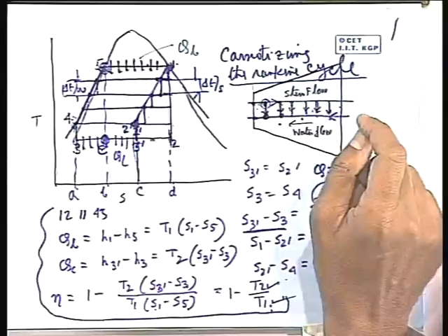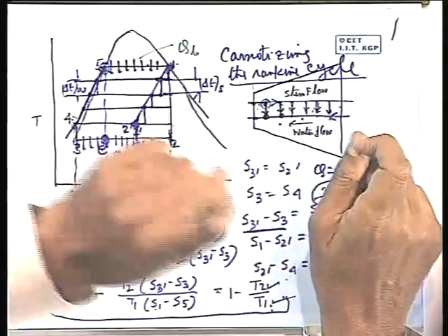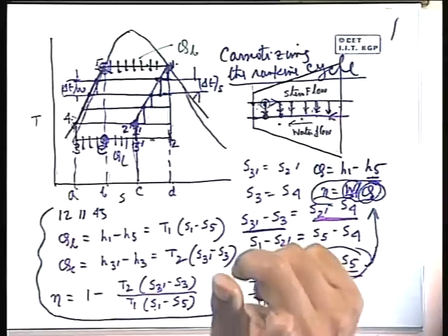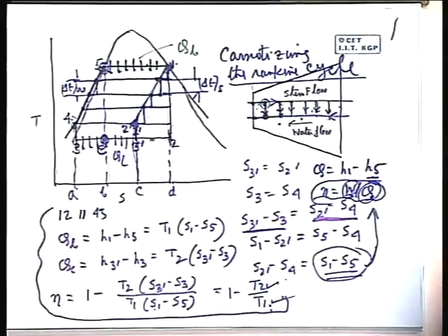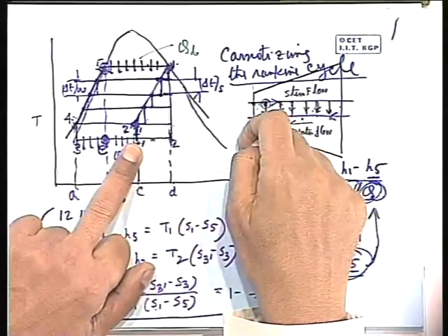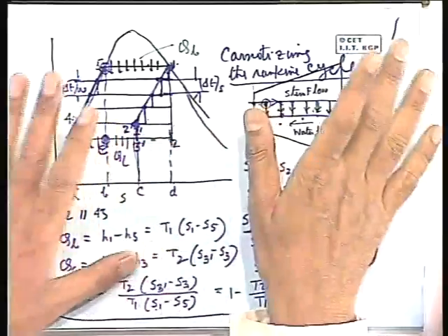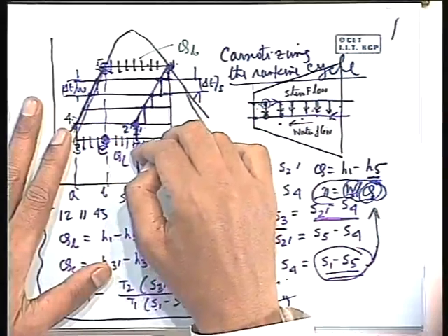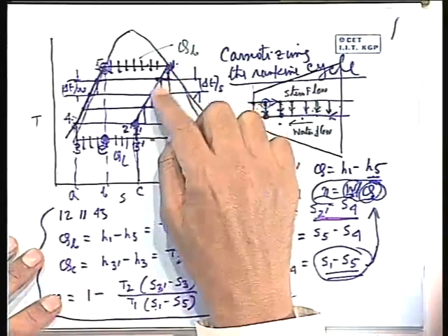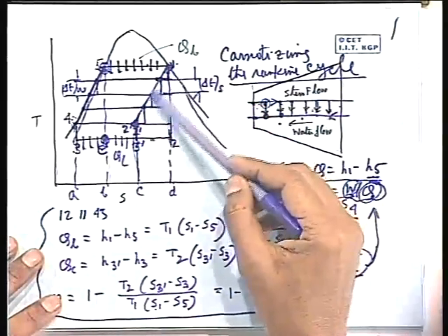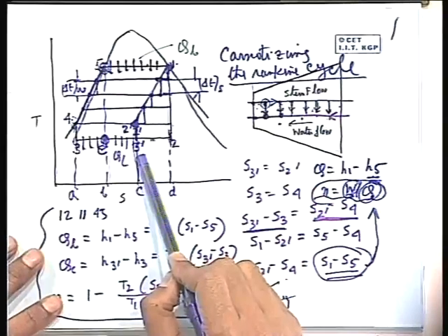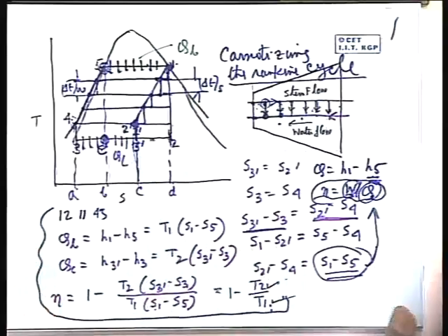Number one, a reversible heating of water and a reversible cooling, that a reversible heat transfer is not achieved. Number 2, it is impracticable to place a heat exchanger tube into the turbine. And number 3 is that even if I allow this process to take place, yes, the dryness fraction increases. But this is a practical limit. I don't bother with that, but still this gives a limit. Yes, the dryness fraction is reduced. That means the moisture content is increased. That is one point, because if you allow this steam to expand in this way, that means in this process of heat transfer, it ends up at a point where the dryness fraction is reduced. That is another point. Very good. So the concept of regeneration is clear.